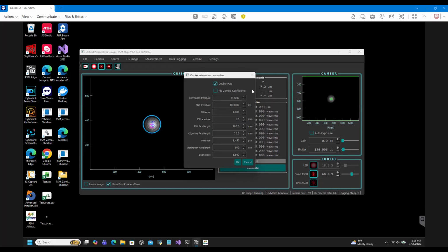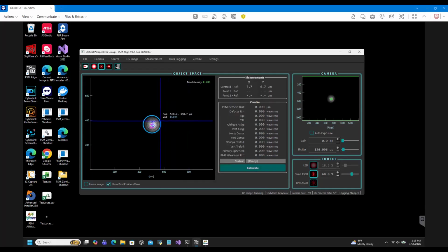But if the beam is stopped by the target, like the mirror is smaller than the beam at the mirror location, then the mirror becomes a stop. And that's where you have to adjust this factor to tell the system there is another stop in the system than the 5 millimeter you have below. It's coming from the fact you are overfilling the part you are measuring. That's just technical detail, but those parameters are entered by the customer when he wants to use the system. It's all he needs to enter. And when he's entered, those parameters will define the size of this circle here automatically, right?